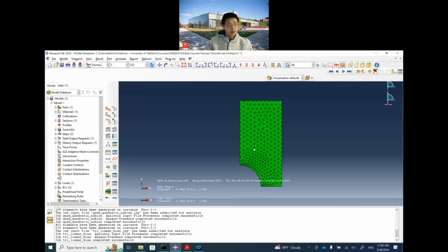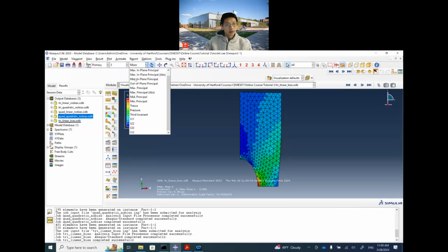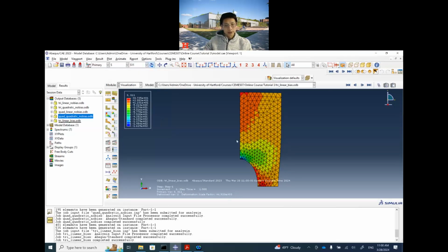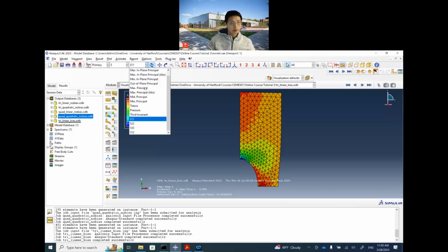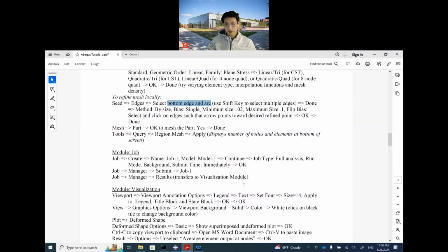It's done. We can check the results. As you can see, the results are also a function of the mesh configuration. If we refine the mesh sizes in those regions, we will have larger stresses there. That's S11; we just look at S22, and that's 4.243.